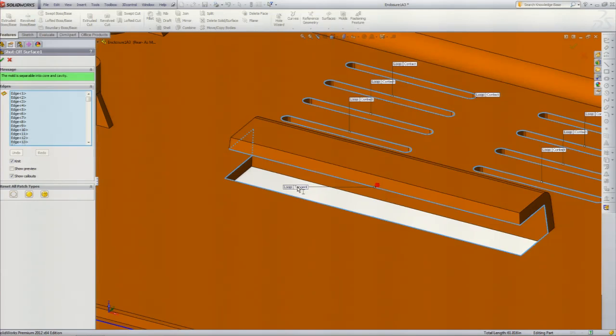I will change that to tangent. You have 3 different types of patches for your shutoffs: no fill, all contact fill, and then a tangent fill. So I did change it to a tangent fill on this particular shutoff.